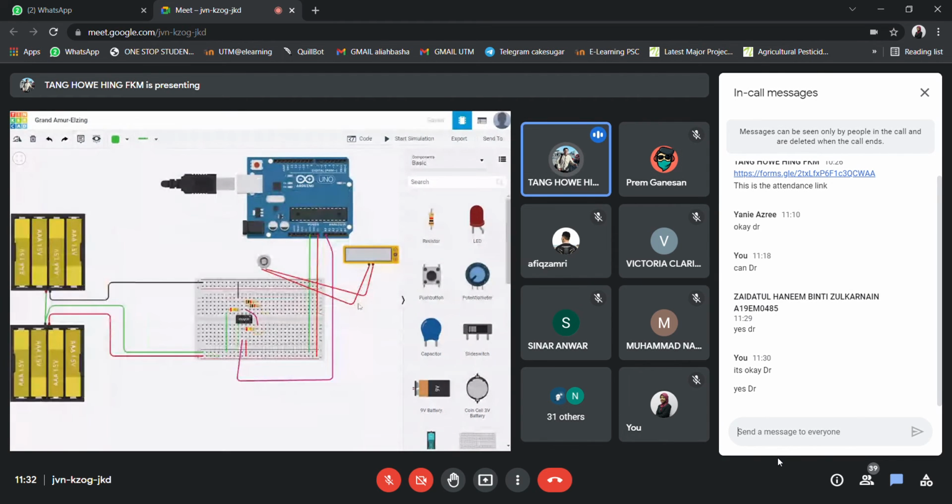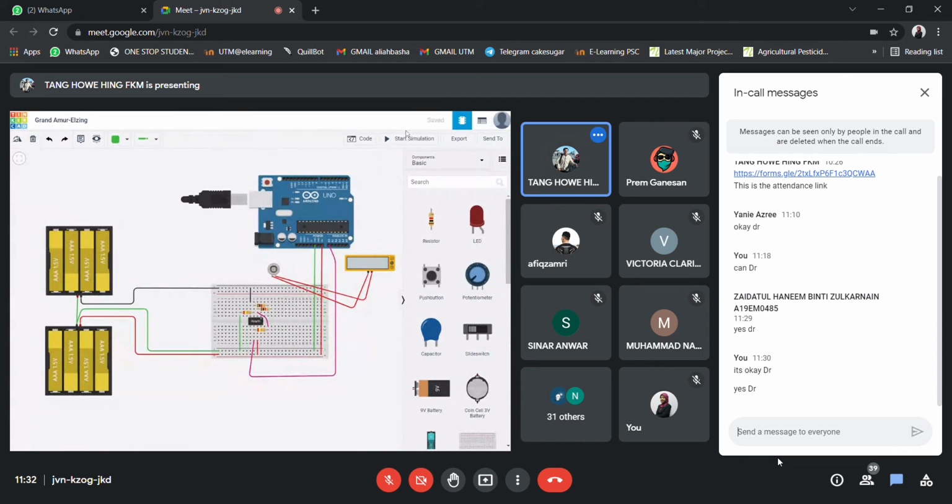All right. So basically, what I want to mention here is that for this photodiode, when it is not connected to any device or resistor, I just measure directly using the multimeter and I get 460 millivolt.